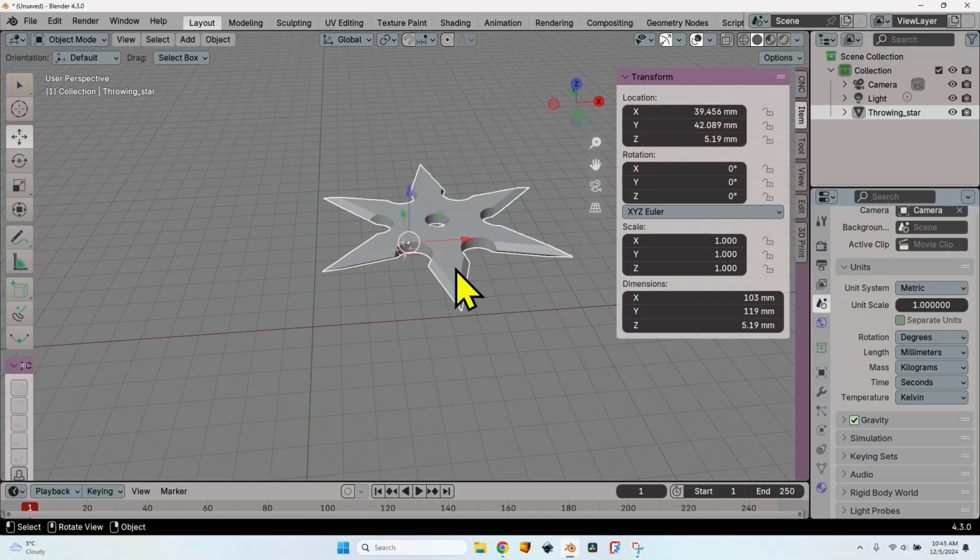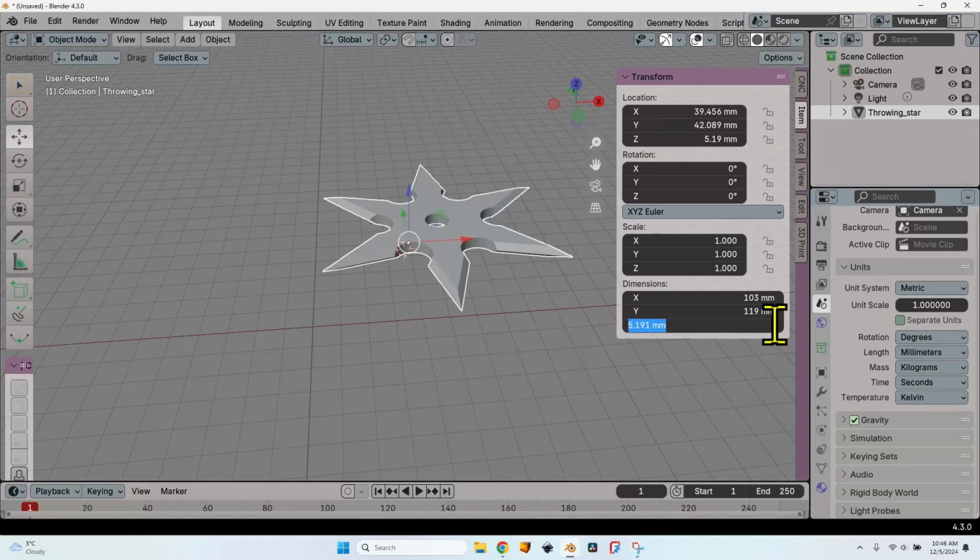Now let's do the part that we are interested in. Let's set everything up in order to generate the G-code for our machine to move to the CNC and mill the actual star out of a piece of plywood, for example. But in order to do that, I need to make a little change. Again, I'm going to use a 6mm plywood. Let's avoid flattening the piece of plywood, it's useless in this situation. So let's simply change the Z dimension to 6mm.